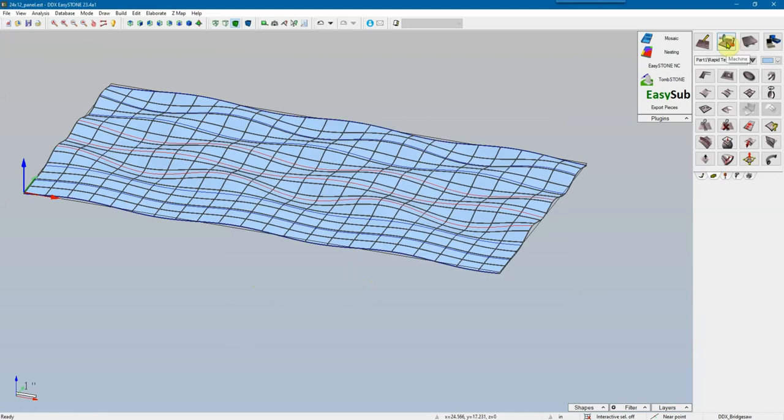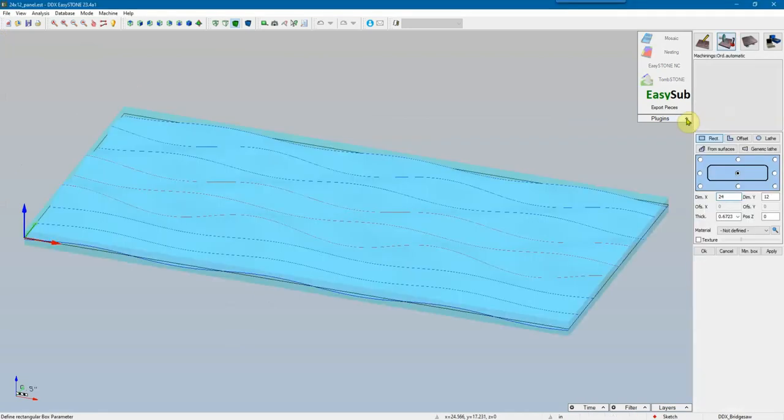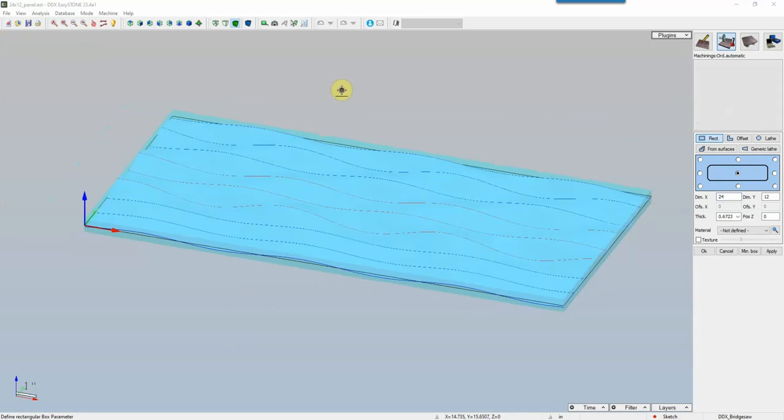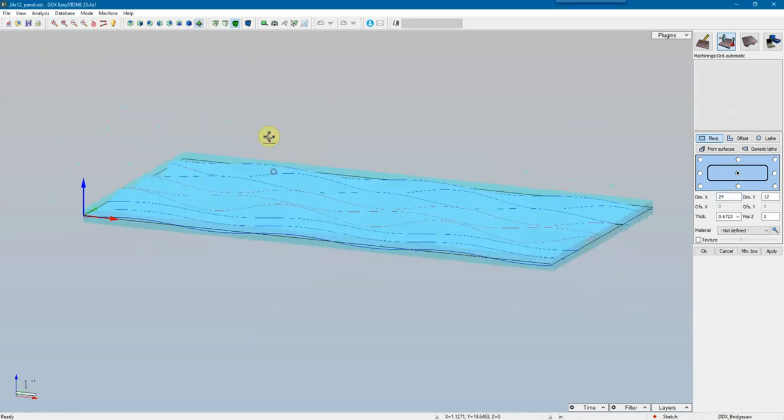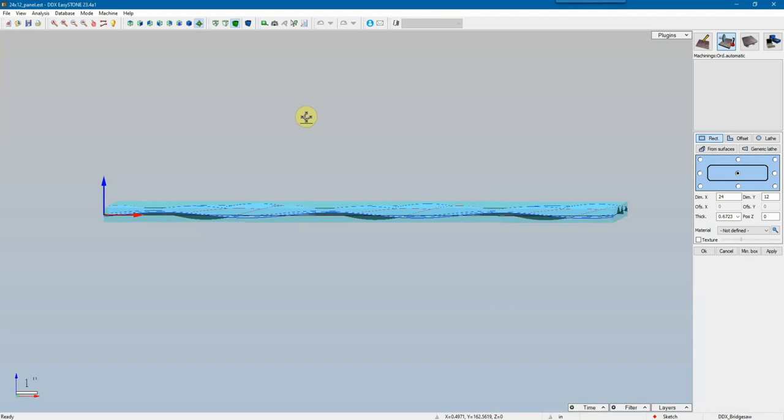And then I'll go to machining. Once in machining, I need to give some depth. My thickness is only as thick as my part is currently. So maybe I have 2-inch material or even 3 cm. And it's looking at the highest point and dropping the rest of my Z down. So it knows that it's only going to work the top.